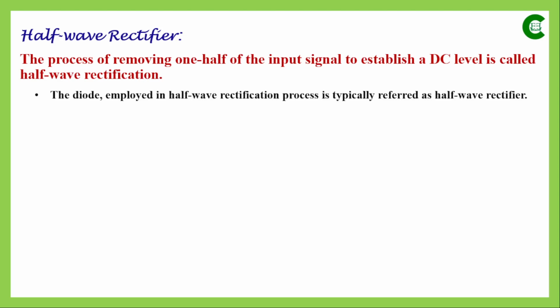Next we will see the rectifier circuit, or rather the half-wave rectifier circuit, that involves a diode, because we will be using the unidirectional property of a PN junction diode there. And we have two types of half-wave rectifiers: positive and negative half-wave rectifier. In the case of the positive half-wave rectifier, in the output we will have all the positive half cycles, and for the negative half cycle part of the input signal, in the output we will have 0 value.